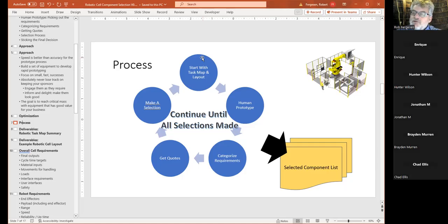And then you also realize you can't use the robot for that directly, because that robot might be doing something else entirely while that little box is moving in front of that sensor. So I would need a special kind of code going on the robot where it's doing something in parallel, or I would use a PLC. And frankly, PLCs are an easier deal. In general, I would suggest if you have a lot of that sort of parallel processing required, always use a PLC. The third area is get quotes.